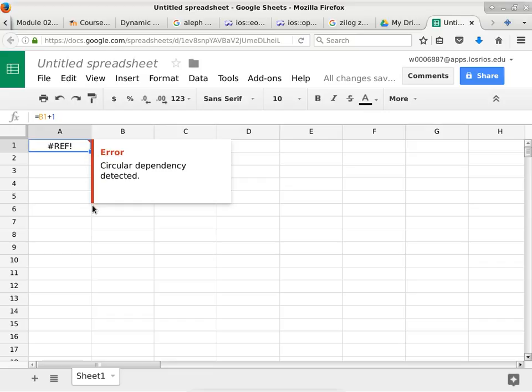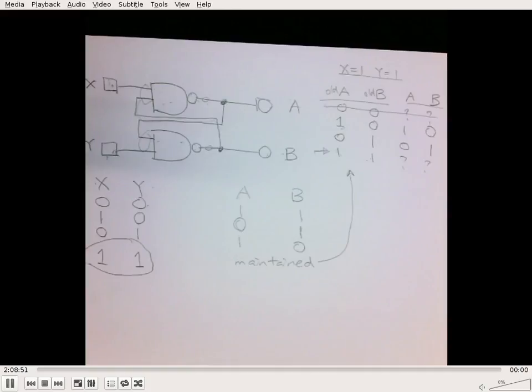So is that answering the question? Yeah, I'm messing with it right now. I don't know most of these components, but would there be a way to use a clock and then some sort of... A clock won't help either. Because the SR latch is not a clocked component. It is a combinatorial problem, and you can put a clock in here, but it's not going to give you the ability to simulate the oscillation.